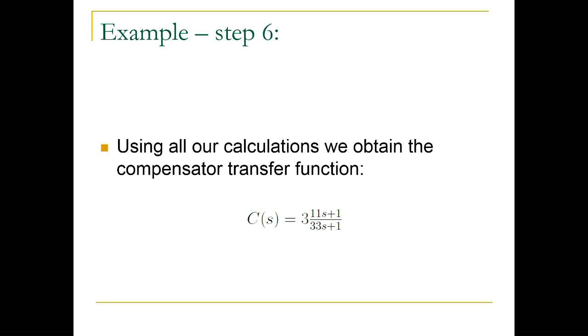Now, obviously, this compensator needs to be verified. We need to plot the true Bode plot for the compensated system to check if what we set out to achieve was achieved. Why may we not achieve these things? All the design steps concentrate on the magnitude or the phase plot separately, but whatever you do affects both magnitude and phase. Because of that, we need to check what we really got in the end.